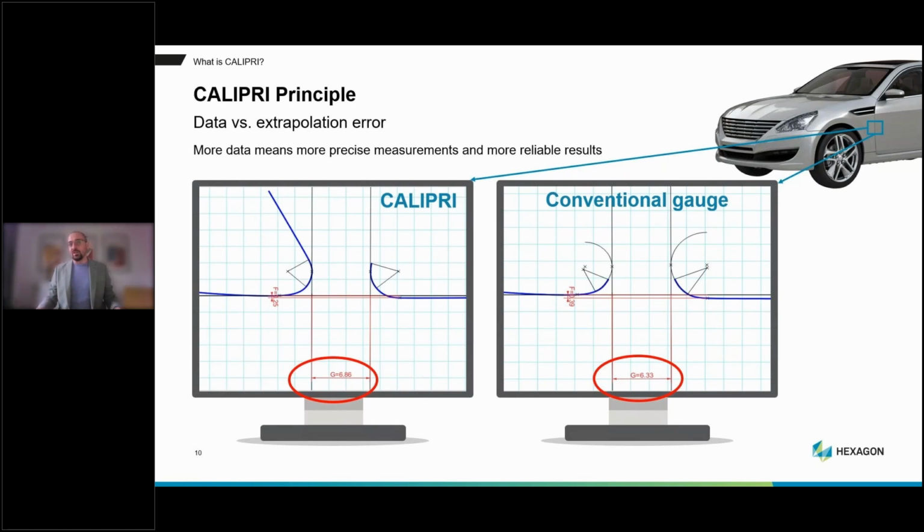What does extrapolation mean? We take our radius and we basically fit a ball or radius in there and enlarge the radius so we have two points facing each other at a very small distance. Depending on which radius you capture, and again, here we go back to what I've said before, the radius isn't consistent. Depending on how much of the radius I capture, those values will differ.